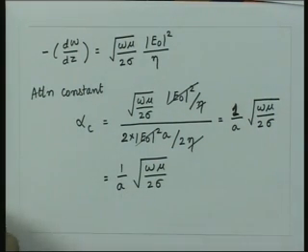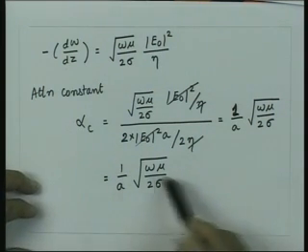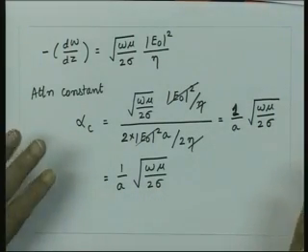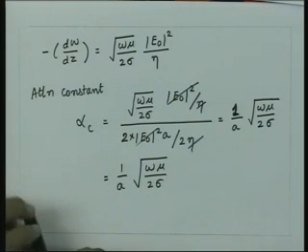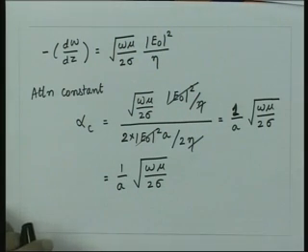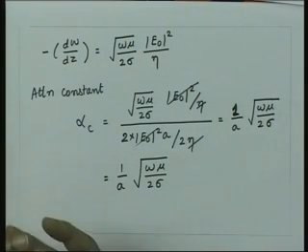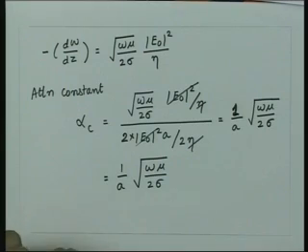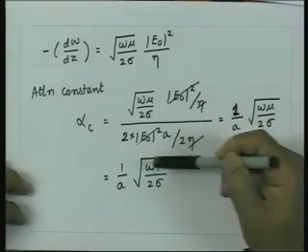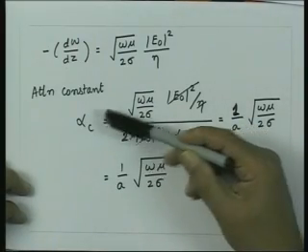Second important thing which we notice here is the attenuation constant is inversely proportional to the square root of the sigma, and that we also understand that if you have a good conductor, sigma becomes large and the attenuation constant will be small, and in the limit when sigma tends to infinity, the attenuation constant will be 0. So if we consider a waveguide which is made of ideal conductor, then we will have the attenuation constant 0. But the important thing to note from this expression is that the attenuation constant is a function of frequency. So as the frequency increases, as omega increases, the attenuation constant increases.